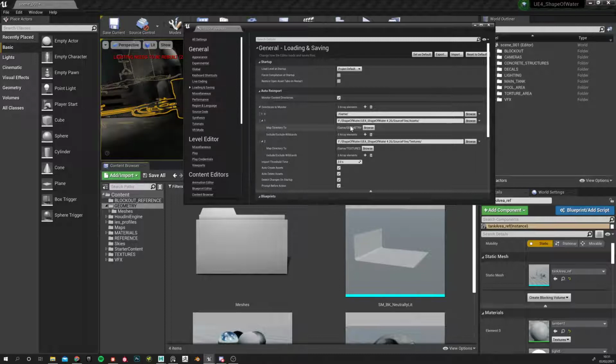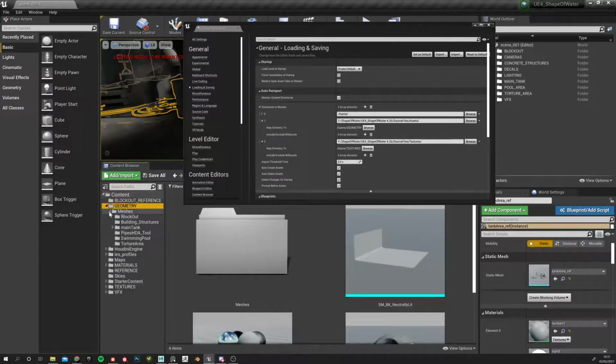Okay. So, like I said, even though I move the assets to, for example, geometry, if I move the asset to here, it automatically will always keep the connection, because once it's imported, it knows that it's connected. Let's say I put it in swimming pool, it's fine. I did the connection, I moved it there. You know that stuff is connected to the asset in the FBX. The changes happen, you reimport it, you automatically fix it up, and then you replace whatever you did. You can change the UVs, change the original geometry, do whatever you want.